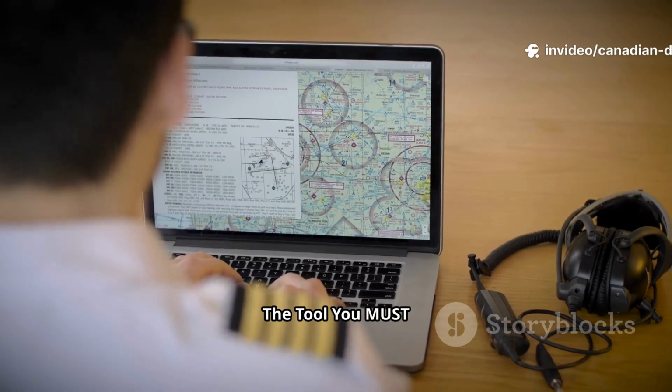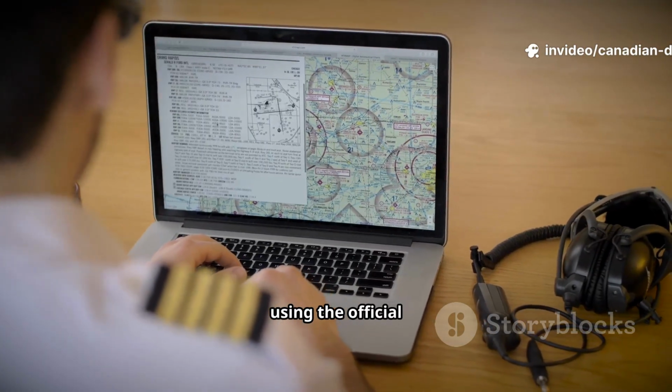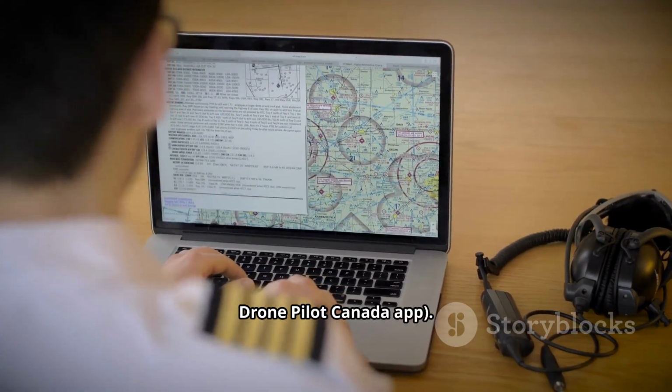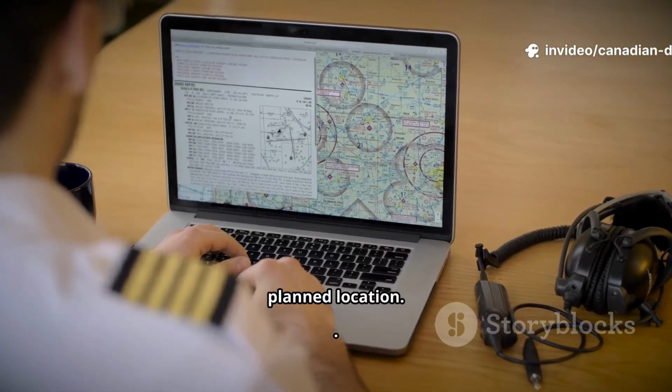C. The tool you must use. You are legally required to check airspace before every flight using the official NAV Canada Drone Site Selection Tool, or a tool that uses its data, like the Drone Pilot Canada app. This tool provides a yes, no, or maybe answer for your planned location.